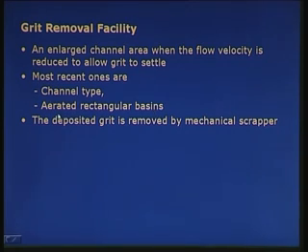The purpose of aeration is that I do not want to make the whole sewage septic, and this aeration will also keep supplying oxygen for the microorganisms that may be present in the wastewater. Aerated rectangular basins are generally used in the western countries. However, in India mostly we have the channel type of grit removal facilities.